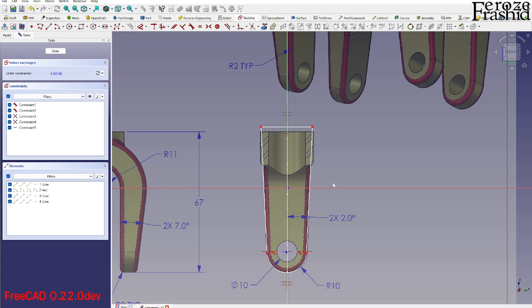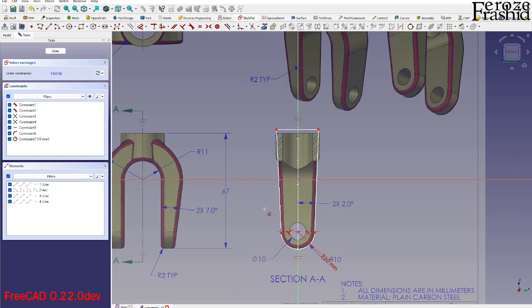Because I'll be doing an intersection, there can be some extra lines here and there, like extra body, but on this sketch it is important that I capture these two edges perfectly, right? On the side by side it should be perfect. Top and bottom, yeah, we can be flexible on that. So I'm going to place it on this axis and apply a 10 millimeter radius, and then this length, the overall length is 67.